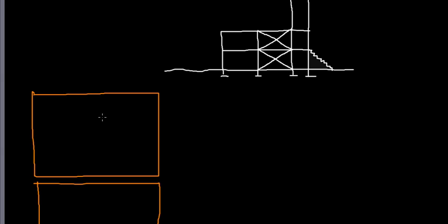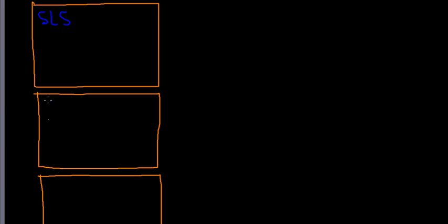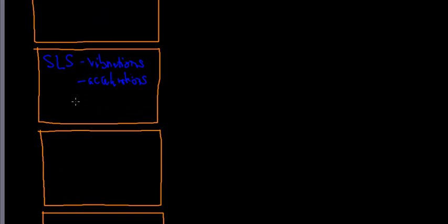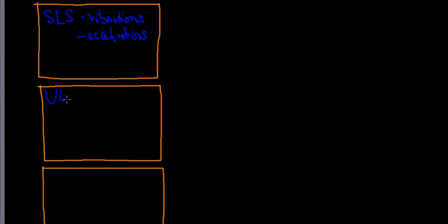And so I've done a little box here, and if we look at the first box, we just call that serviceability limit state. And then the second box again would be serviceability limit state. However, let's call that vibrations and accelerations. Well, the first serviceability limit state would really focus on static deflections. So we have to check those two boxes, and then later on a very big one would be the ultimate